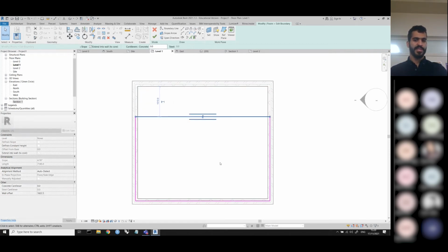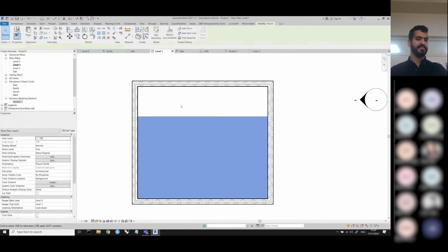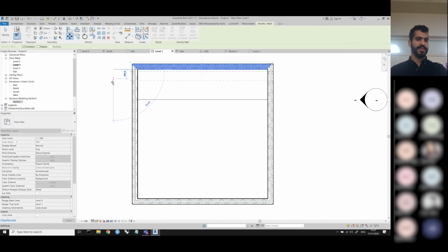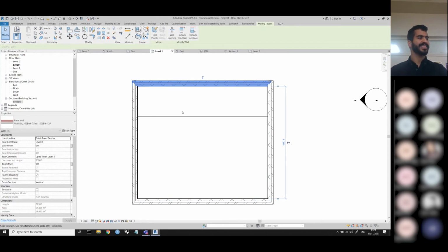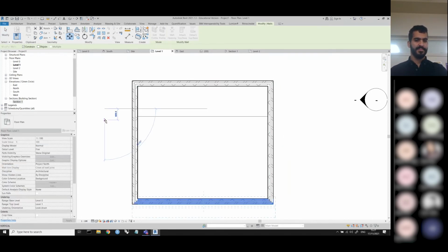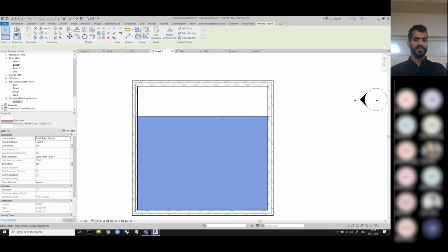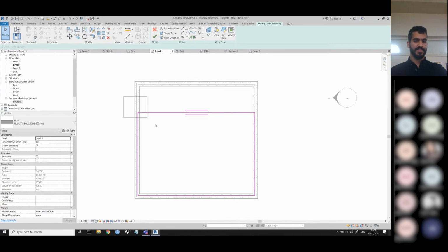So these walls are linked, the floor is linked to my wall. If I change it here, okay, now I have a gap in my floor, right? And this is not constrained anymore. Well, it is constrained, but to a set distance. If I move this in, it's not constrained to here, right? So an interesting way to work with this, and this is something you often have to do when you model something more complicated, is align, which is here.